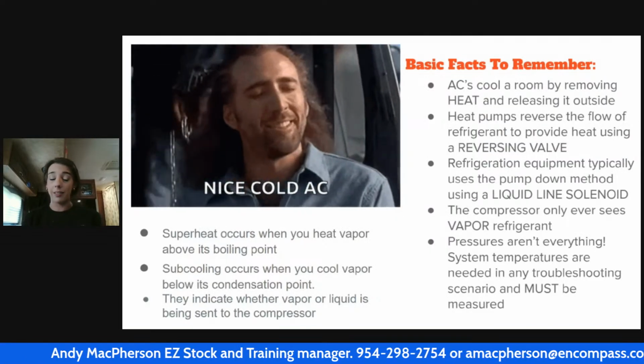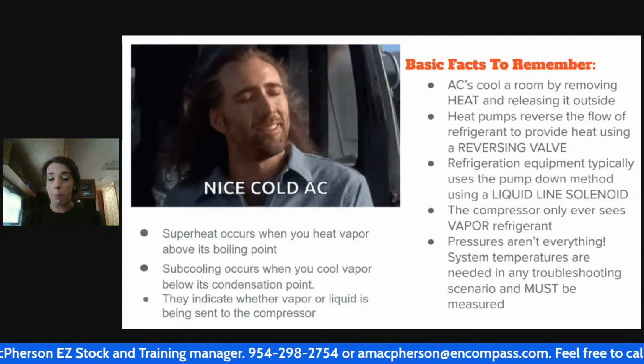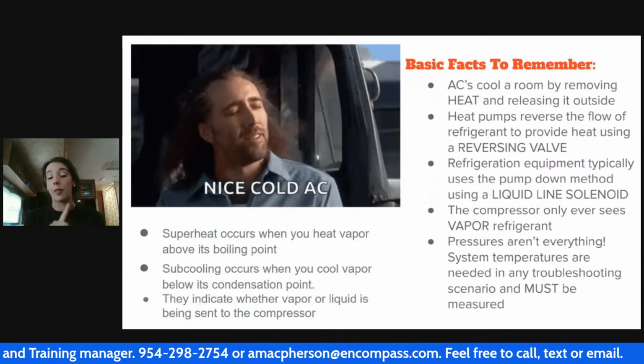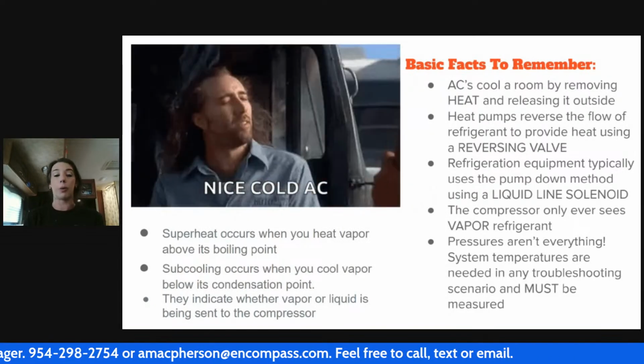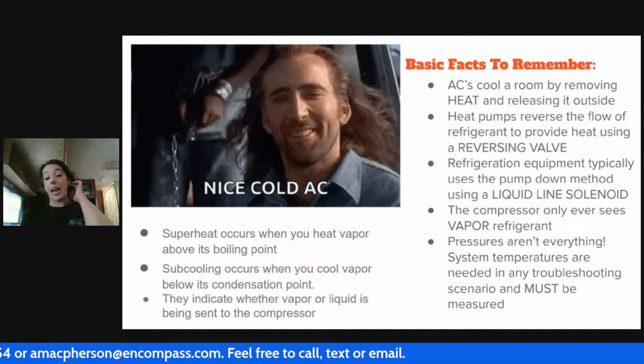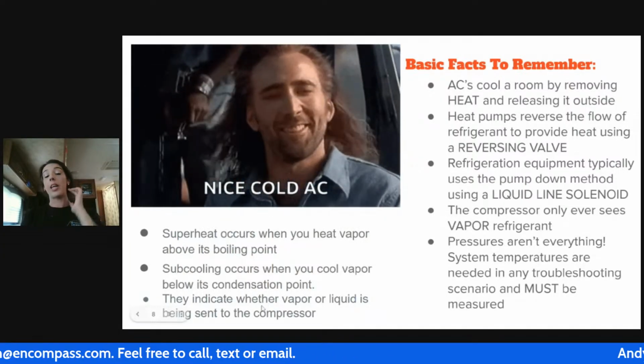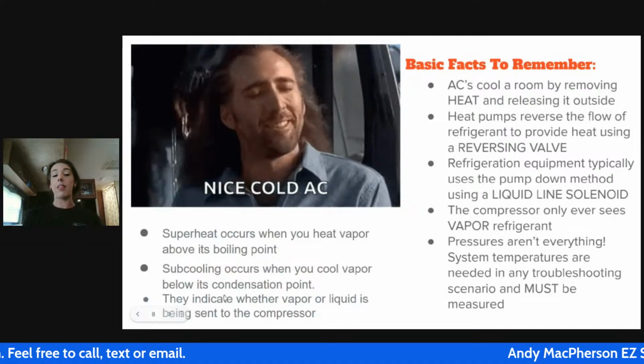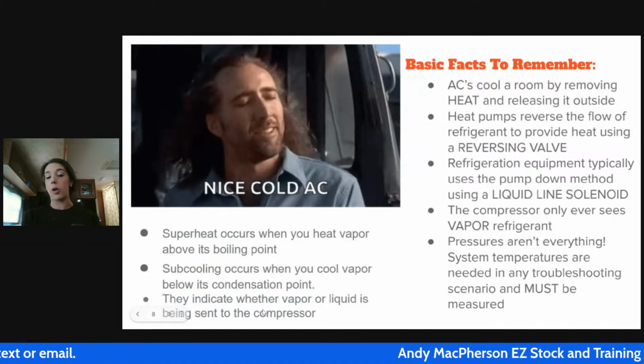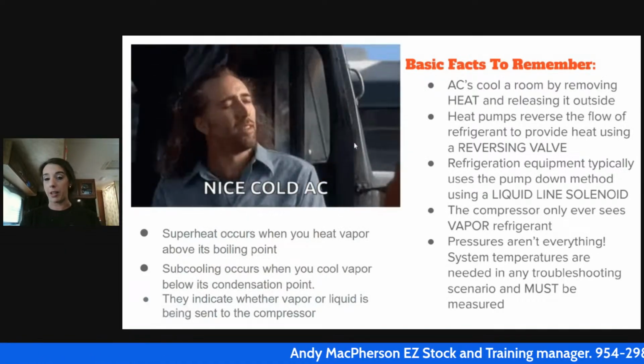It's going to die. And compressors do not die on their own. They're murdered. And that is the number one way that they're murdered, is by flooding them with liquid. So again, depending on what your subcooling and your superheat is, that is indicative of how much vapor or how much liquid is heading back to the compressor.